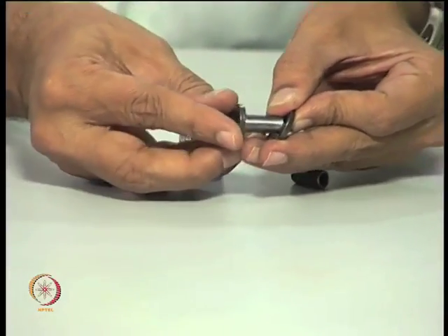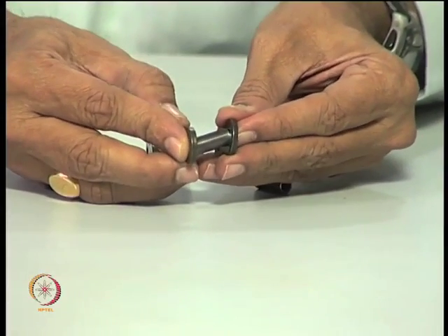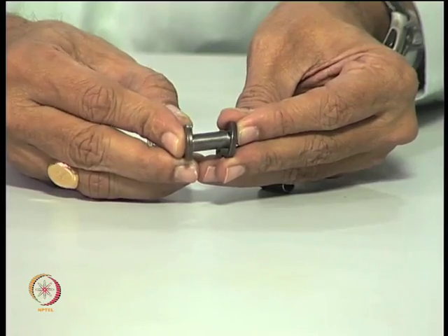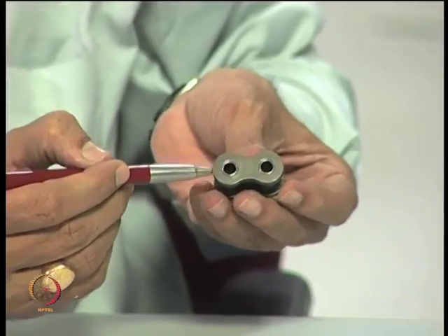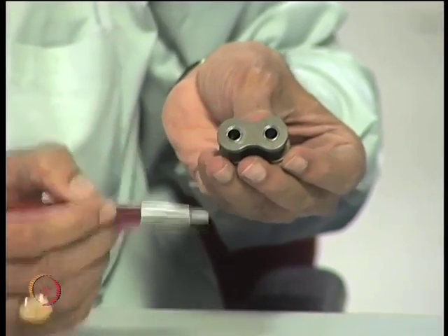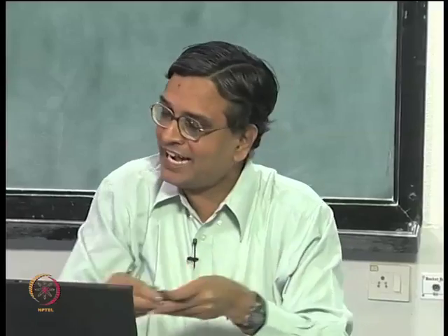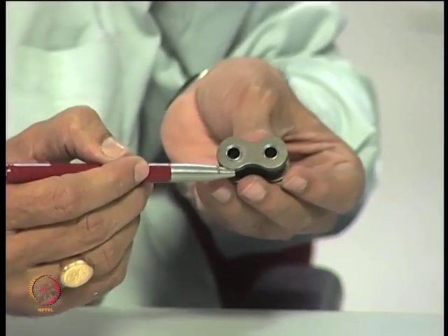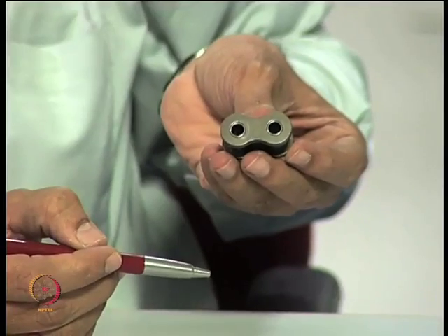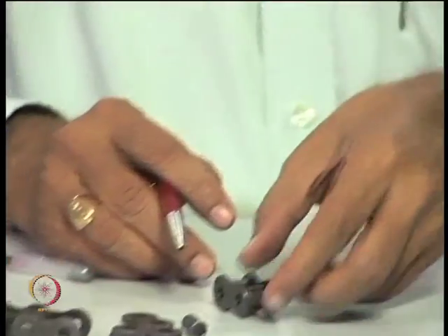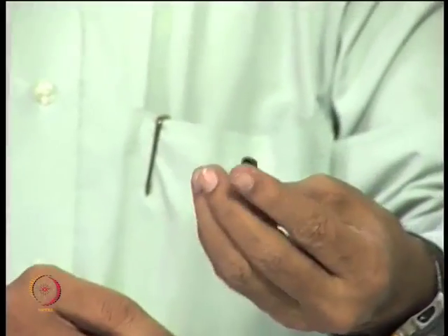and these plates are brought together by putting the appropriate bush, and the bush has to stay in place. So, you have an oversized bush and this has to be inserted. So, this is done with an interference fit. So, apparently I do not have any external load on this chain link, but because of the way it is manufactured, you have stresses developed, you have a bush here, you have stresses developed very prominently here, and it is comparable to the service loads. The stresses developed are not small in value, they are comparable to the service load.